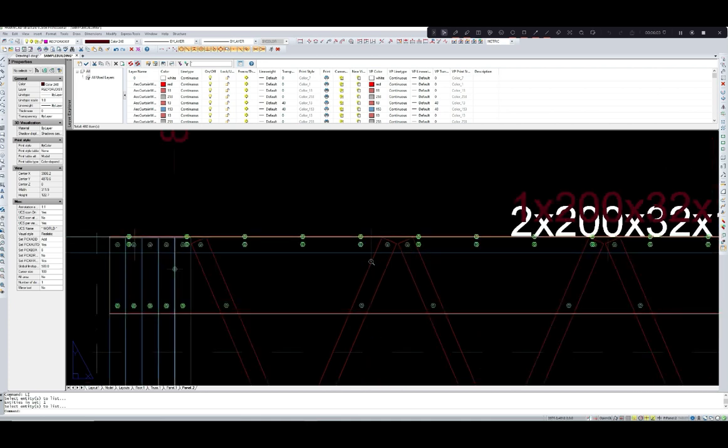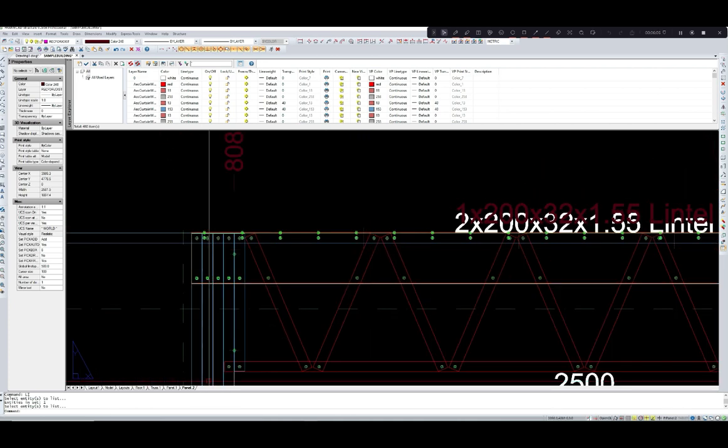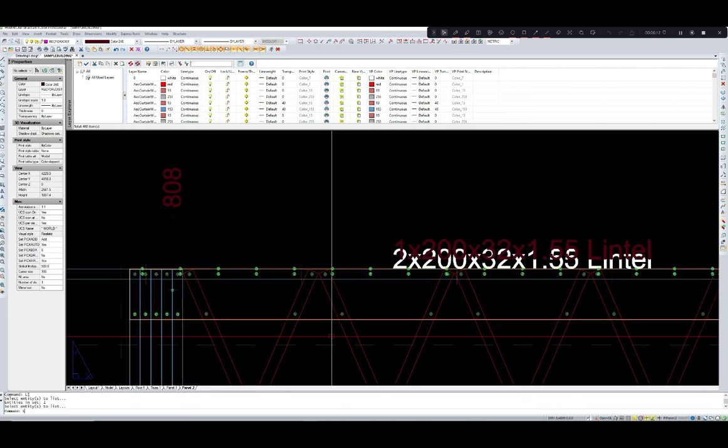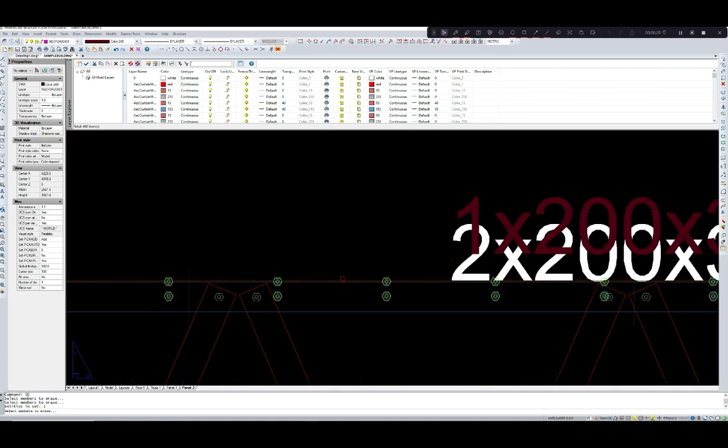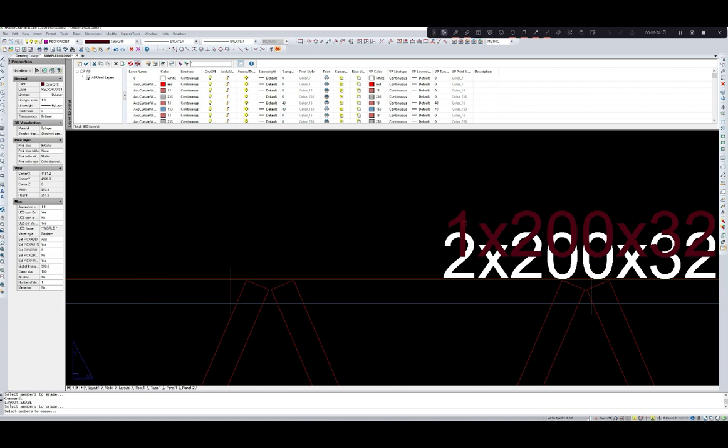If you have to make it bigger one, then let us erase this lintel. SE is the command to erase this lintel. SE, special erase. Again SE, enter.